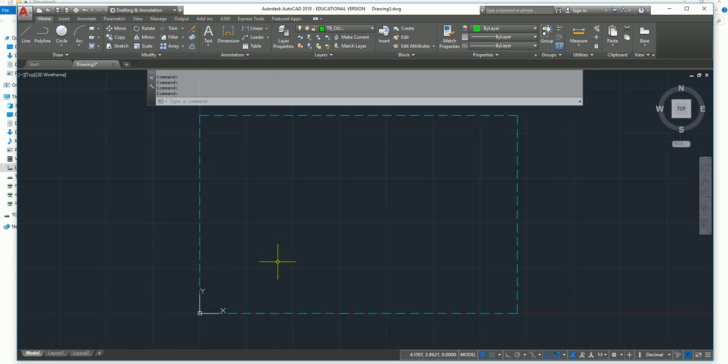Now what I want you to do is draw. We'll do a rectangle. Just like current, right? For the layer? Yes. So it should be on TB outline. So I want you to type 0.25, comma 0.25. So 1/4 by 1/4 for the start point. What was that again? The start point of your rectangle. Yeah. 0.25, comma 0.25. Then enter.